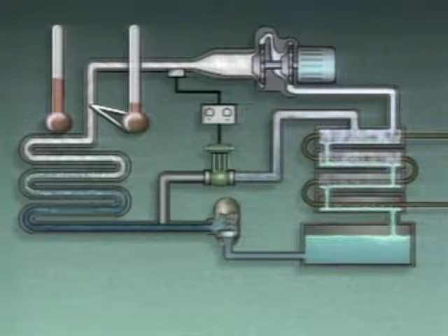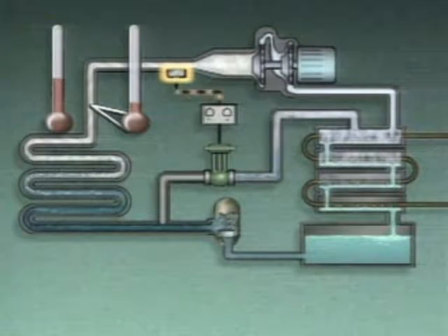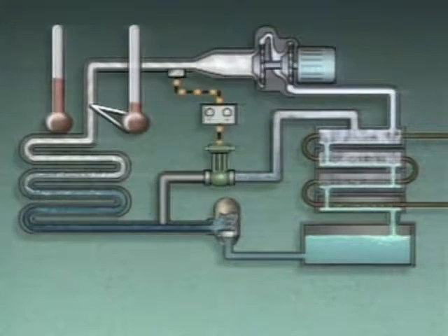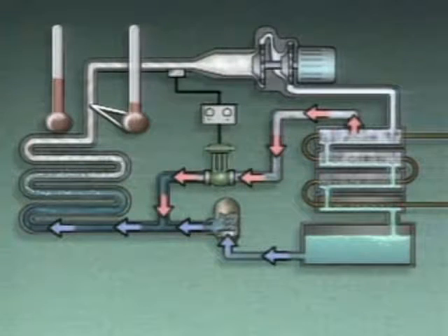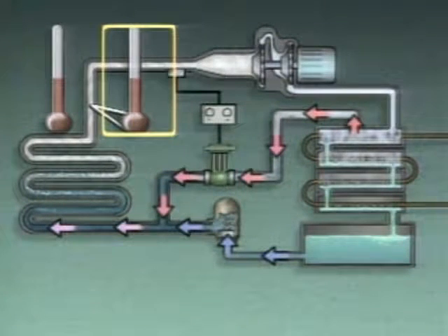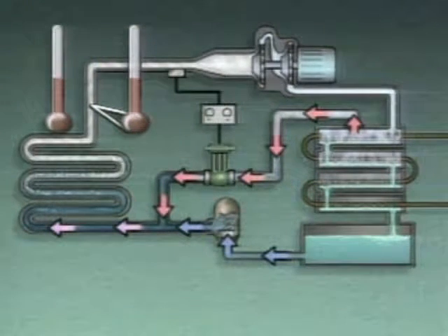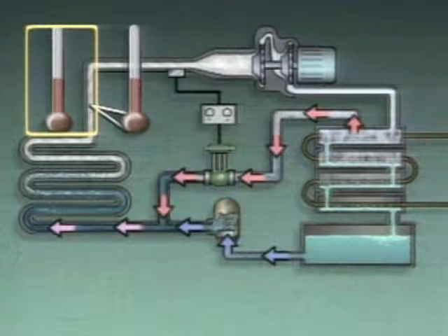When the temperature of the refrigerant flowing to the compressor drops, a temperature sensor sends a signal to a controller, which in turn sends a signal to the bypass line control valve, causing it to open slightly. This allows some of the refrigerant from the discharge of the compressor to be routed to the evaporator. This warmer refrigerant mixes with the refrigerant leaving the expansion valve and increases its temperature. As a result, less heat is removed from the substance being cooled, and its temperature increases back to the desired